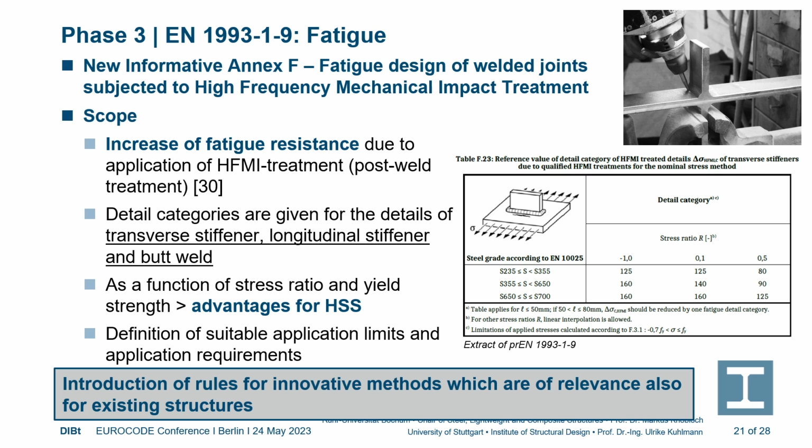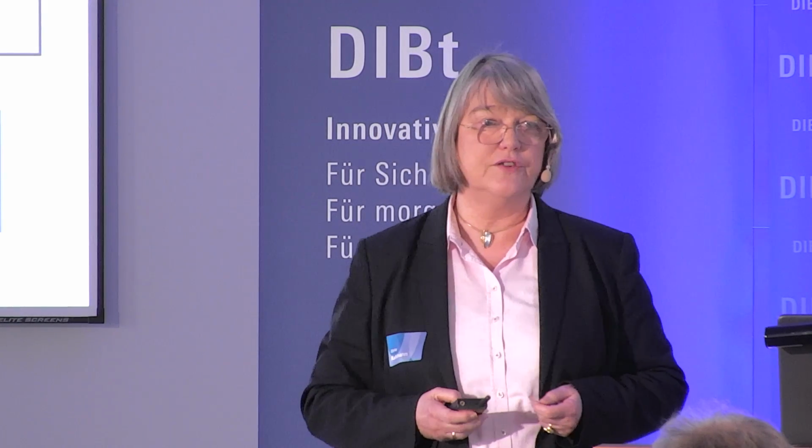So it's a new method, but it is especially interesting for high-strength steel, because the use of high-strength steel under fatigue is not of any advantage normally. But having this treatment, you get a real profit from that. And personally, I think that these innovative methods also will be of importance for what we heard already, for the renovation, rehabilitation of existing structure.